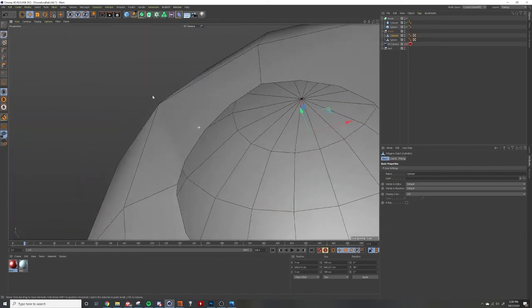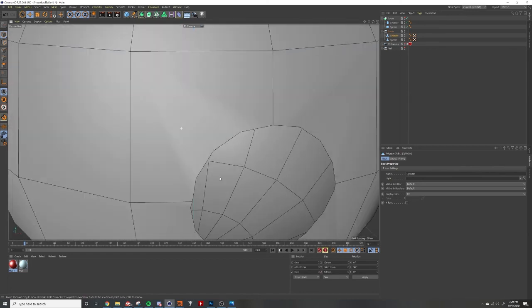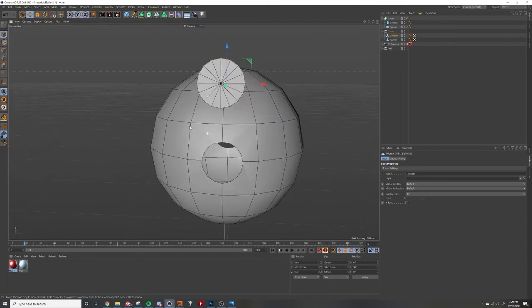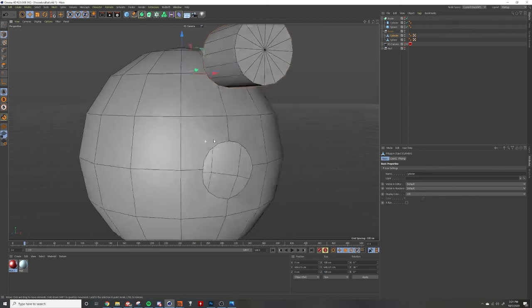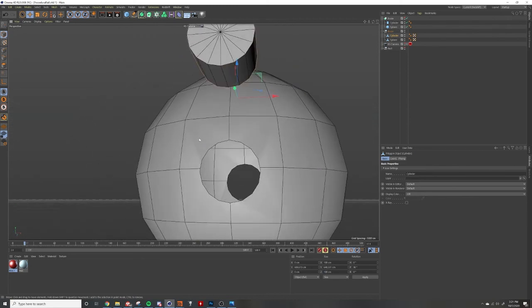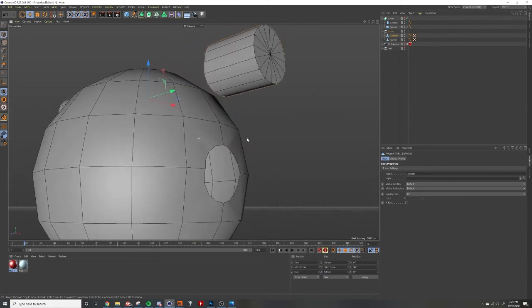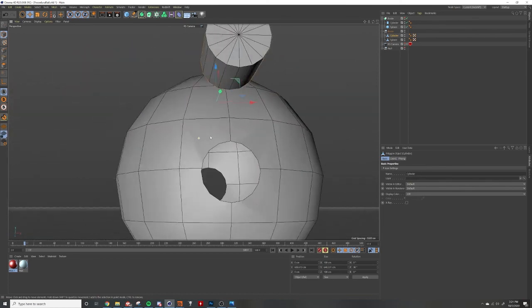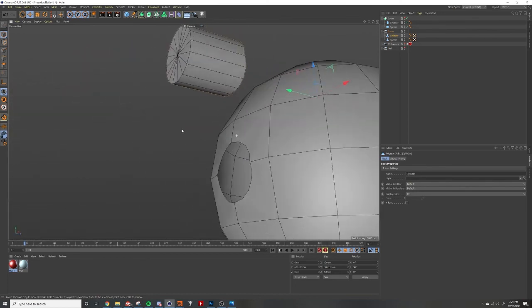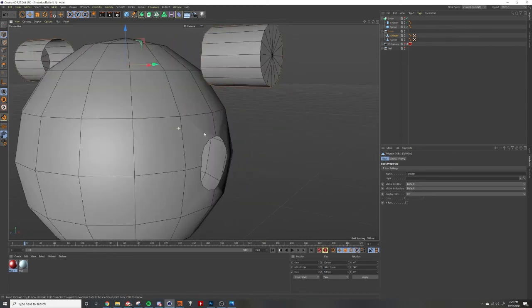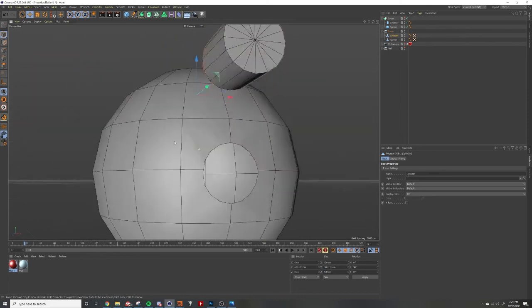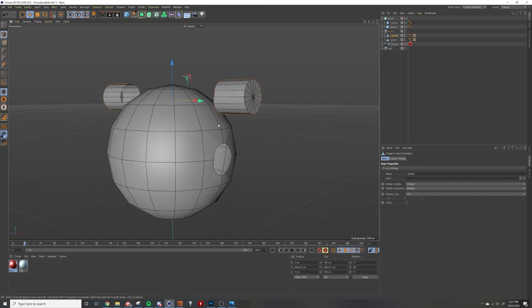So it's created all these little things, and you can see that it's deforming the light scattering. You can see these little polygons that don't exist, but they're there because the shape is warped and it's messing up the geometry quite bad, which is most of the time why you don't use a Boolean, because it will just destroy your geometry.